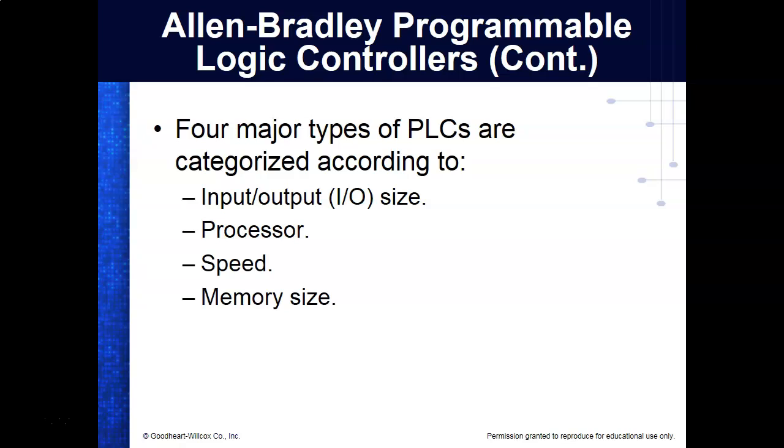Fixed PLCs, though, you've got to remember, once you buy them, you've got the processor, you've got the speed, you've got the memory, and you've got the inputs and outputs, and you can't add anything, you can't expand them at all. So the big advantage of a modular PLC is that we can expand them. The big advantage of a fixed PLC is that it's cheap. But you get what you pay for, and a lot of times that's all you need. So that's it.